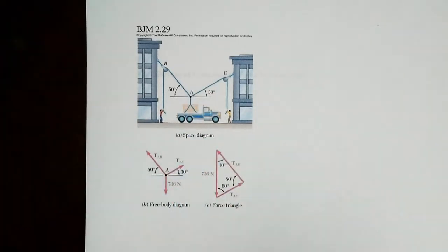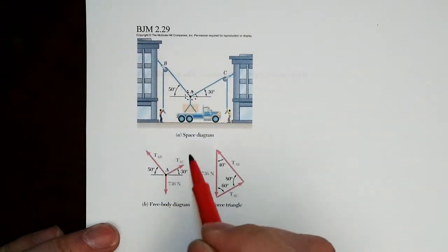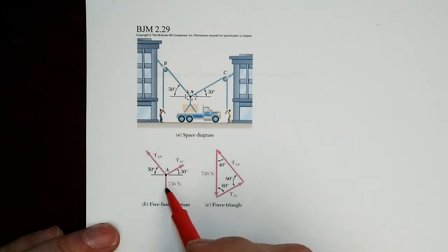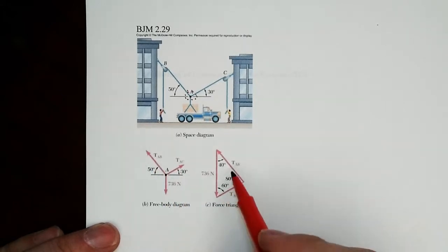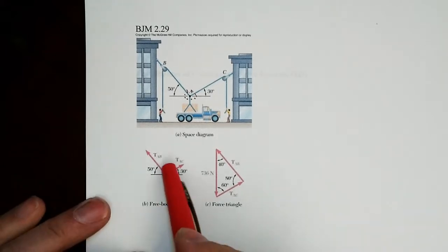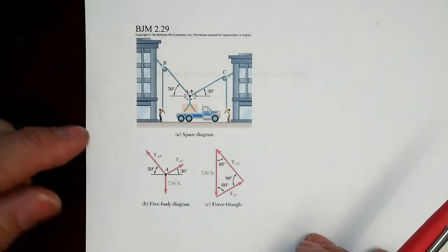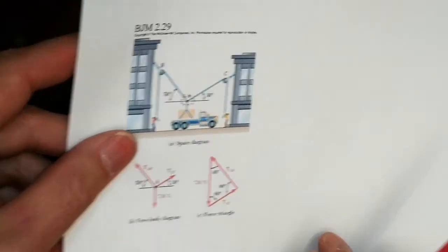Let me zoom in. We're cutting right around here, creating the free body diagram. There's our point A, and tension in one cable, tension in another cable, tension in the third cable, and this force triangle will be a statement of equilibrium. That's where we are headed. In equilibrium, we don't have any acceleration, so F equals ma means the sum of those forces must be zero, and that's how we represent, vectorially and rather graphically, what's going on with those three forces. We'll get into more of that in just a bit.